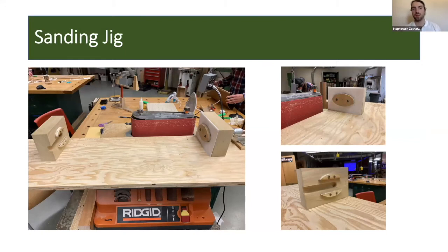The biggest problem that we had with the sanding jig was how we were supposed to index it. So what we came up with was a stationary block on the left with a notch cut out of it for the wires to fit into. The block uses the cutouts from the base parts to prevent the lamp from twisting. And on the other side, we have a block with a similar indexing system, but instead of being stationary, it slides back and forth to clamp the lamp into place while we're sanding.